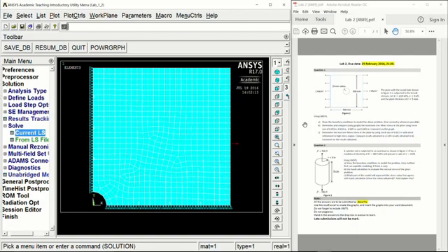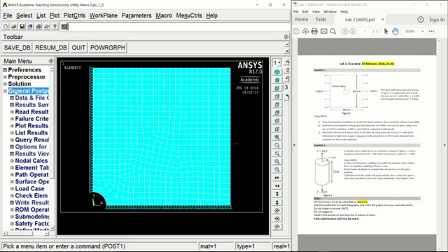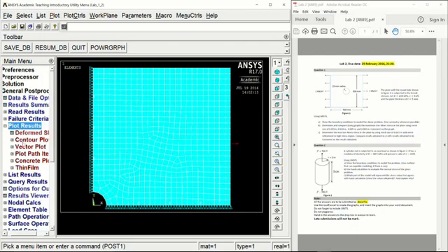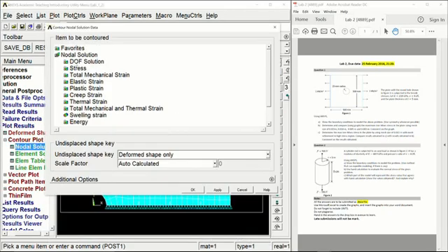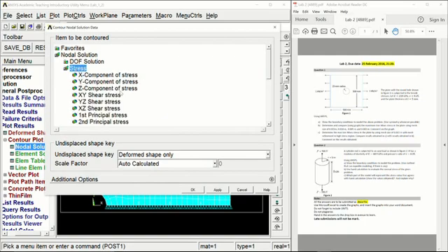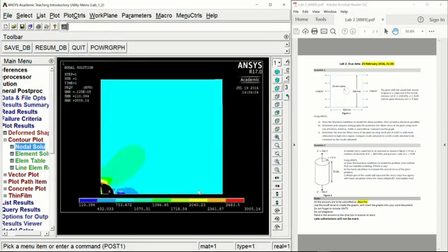All right, next C asks us just to determine the max stresses on our plate. So to do that, we are going to close down the Solutions tab, open up General Postproc, and we are going to go down to Plot Results, Contour Plot, Nodal Solution, and we're going to select Stresses here, and we're going to scroll down and select von Mises stresses, click OK. And here we'll get our color contour with our plate.